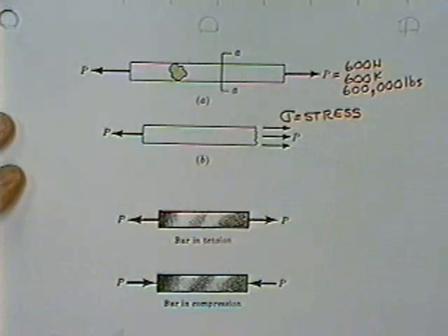Stresses, loads don't actually break things. It's really stress that breaks things. You give me a large enough member and I can hold up just about any load that you're willing to buy that much steel to hold it up. But if the stress level reaches a certain level, then the structural member fails, and most all design is based on that fact.